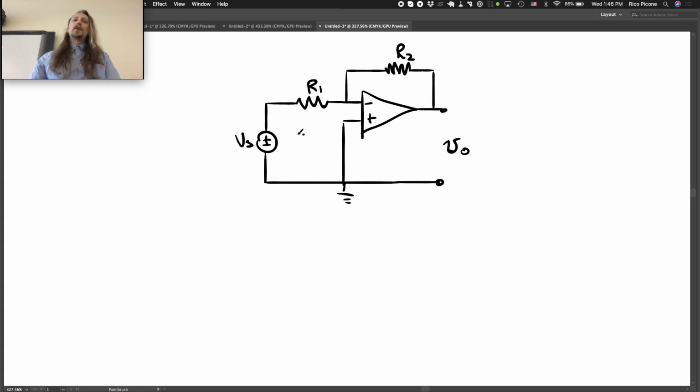So we can go through and do different loops and all that, but the place to start whenever there's an op-amp is to say, okay, what are the assumptions we're going to make about the op-amp? First of all, we're going to assume that it doesn't draw any current, right? So we aren't expecting any current to go in through the plus or through here. So no current. I equals 0, I equals 0. We're also going to assume that V plus is approximately equal to V minus.